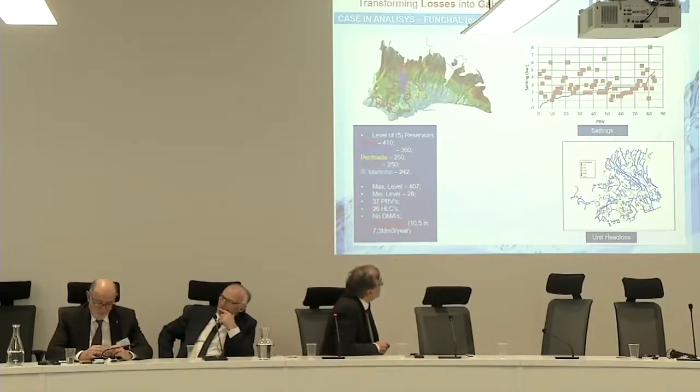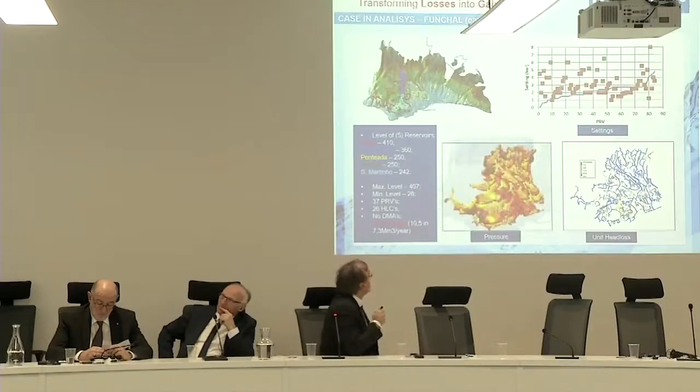And the head loss here, the unit head loss, above 5 is only the blue ones. The other ones, the red, is above 20 meters per kilometer. It's crazy. It's impossible. It's unmanageable. So we have to solve the hydraulic problem.